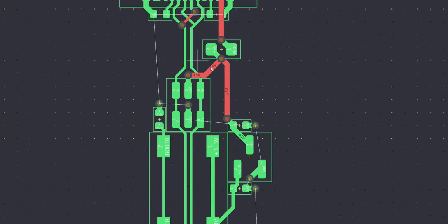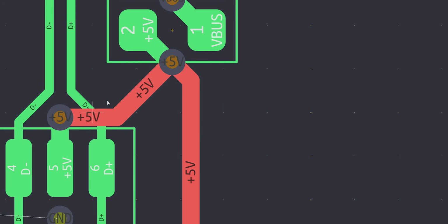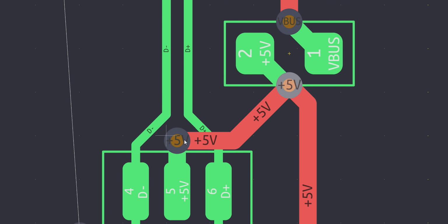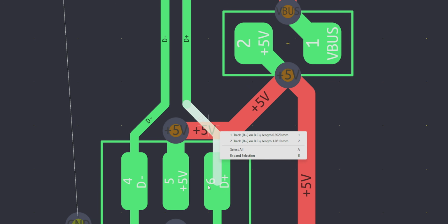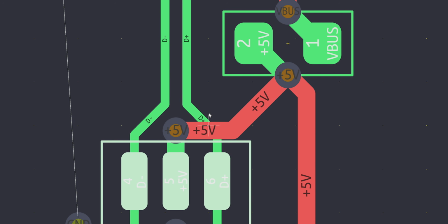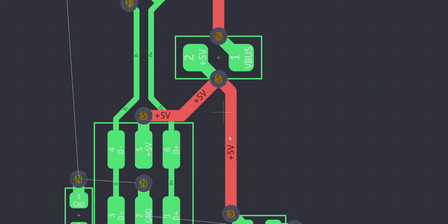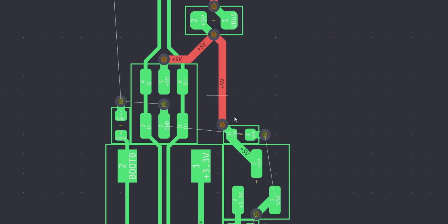So you can see that I'm routing my voltage as far away over here. And you can also see here that I'm pulling the voltage down and then I'm running it horizontal instead of parallel with the data line as much as I possibly can. That's just because if this did run directly over here, you'd run into the issue of possibly having problems there. Now, I think data lines, specifically data plus, data minus, have something to do with impedance control. It does prevent this issue, but for normal matrix lines or any of your reset stuff, you want to keep it away from power there.